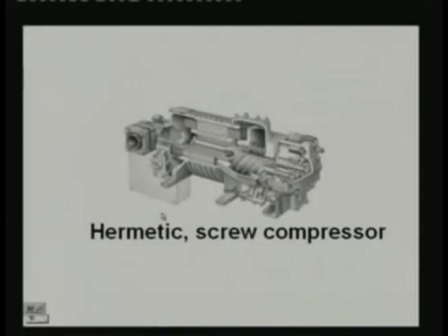This picture here shows the photograph of a hermetic screw type of compressor. As you can see here, a screw compressor uses a helical screw and a mating component, and the rotation of these helical screw and the mating components gives rise to suction and compression effects.